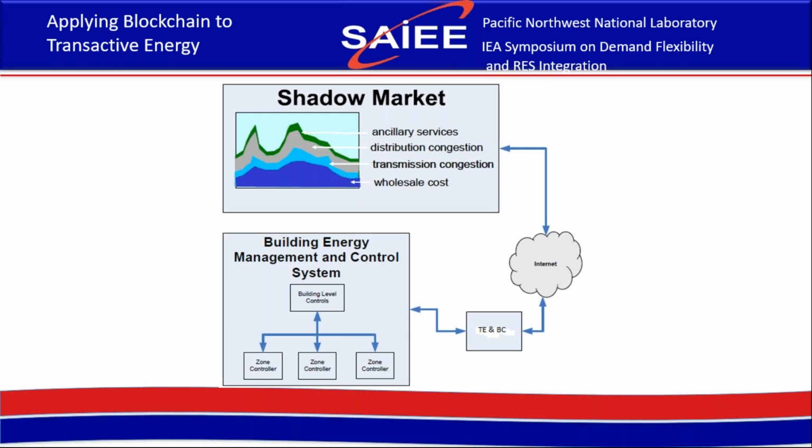What will happen is that your HVAC system will move from 23 maybe to 25 or 26, so it will start consuming less. By consuming less, you are selling that power to whoever wants to buy. So now you can see a system where your demand response is actually generation.